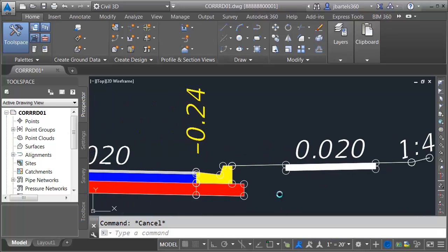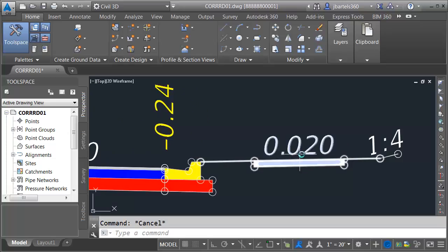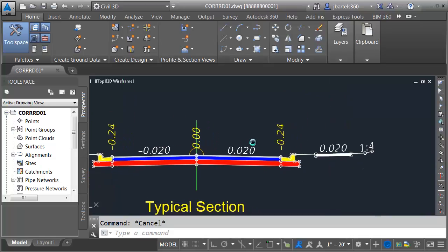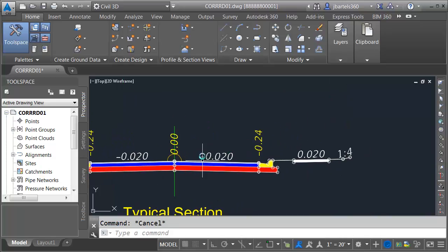These come in handy when we're labeling. For instance, somebody labeled the sidewalk link. Somebody applied a label to the top of pavement link here. So when we create cross sections later, or whenever we need labels for these things, we can go through and say any link that has a pave 1 code or a sidewalk code, I want you to put a grade label on there.